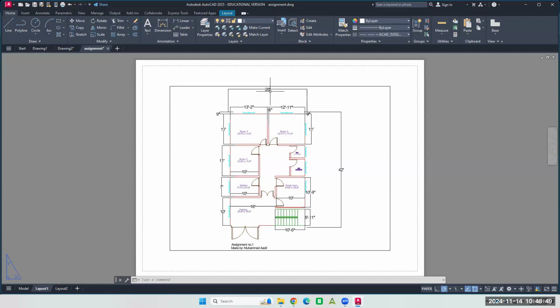You go into the properties of the dimensions, make them annotative, like you know how, set their text type to what you want, make it work with layout, right? Just kind of standard stuff that we should just do over and over and over. It's good practice. I think I said 0.125 on the dimensions and 0.2 on any other notes. So all we're doing is we're just copying a file and then adjusting the dimension and making our own. Yep, that's it. Should be a simple, straightforward project.